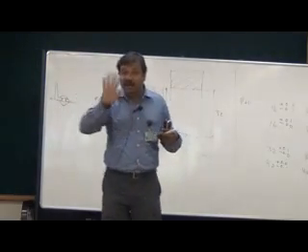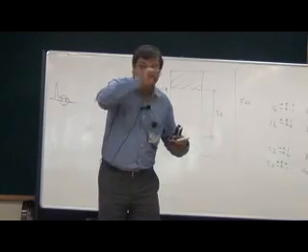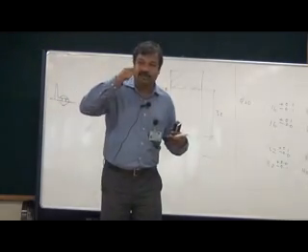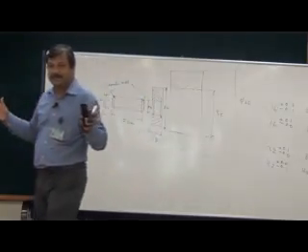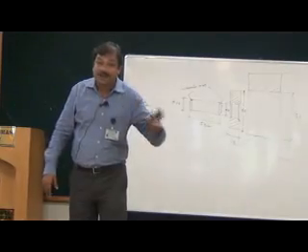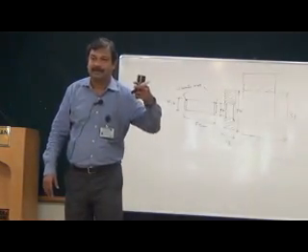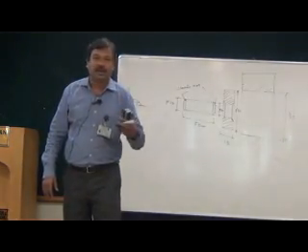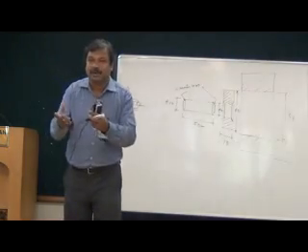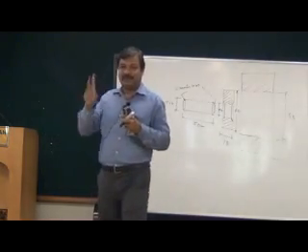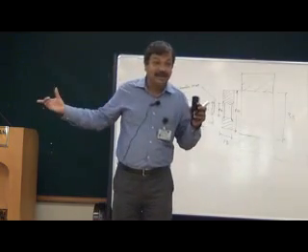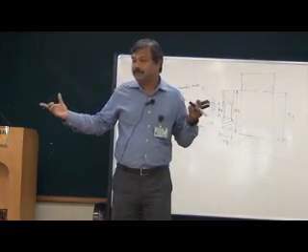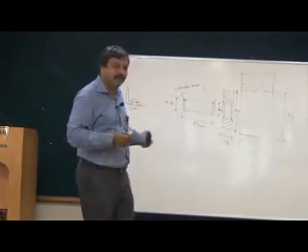During riveting, I don't want it to be strong, because I would have to apply extra force. During riveting, it is very soft. But after some time, what happens? It age hardens. It undergoes a process called age hardening or precipitation hardening, and it becomes strong. I have achieved two things. One is airtightness. Another is age hardening. So this is done in aircraft riveting.